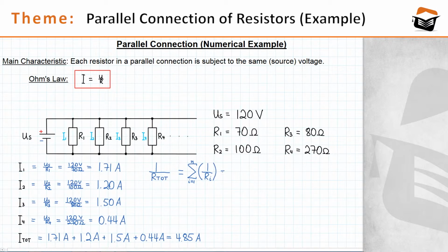And in our case, summing up the inverses would give us 1 over R1 plus 1 over R2 plus 1 over R3 plus 1 over R4. And you may have noticed that sometimes I said resistors and sometimes resistances. So to clarify, a resistor is the electrical component. A resistance is the value, well, is a resistance. So the number of ohms.